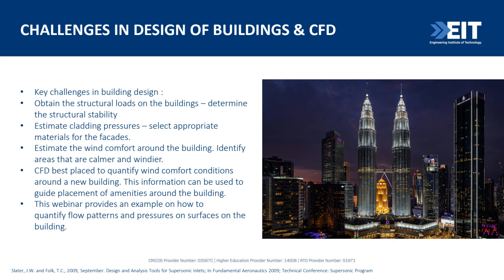Yep. And also we have to look at appropriate pressures on the surfaces of this tower. So, when the wind is moving past it, what thickness of glass is necessary to withstand these kinds of wind loads? If you have too thin a glass, you'll see that it'll start shattering. And you might also need to design it for extreme wind events. What if there's a hurricane that is going through this path? You don't want the whole glass panels to be shattered, because it'll take a long time to replace them.